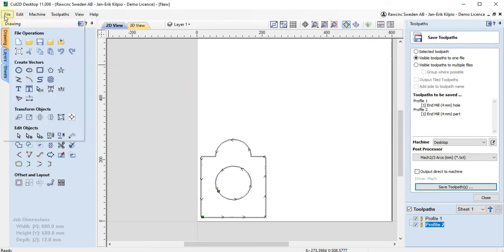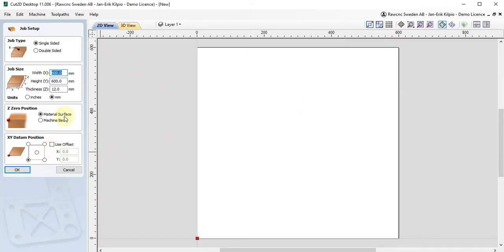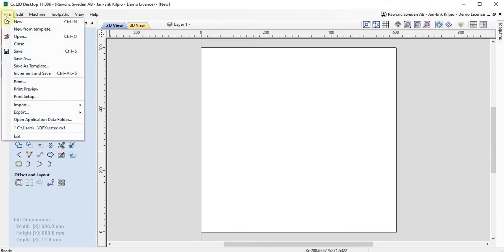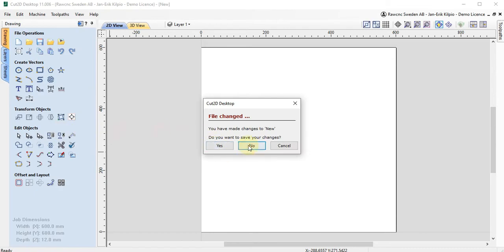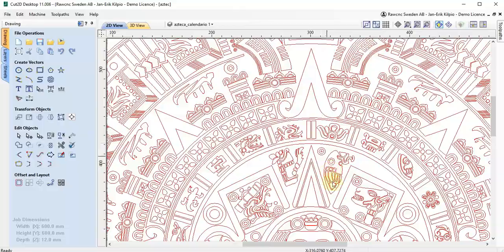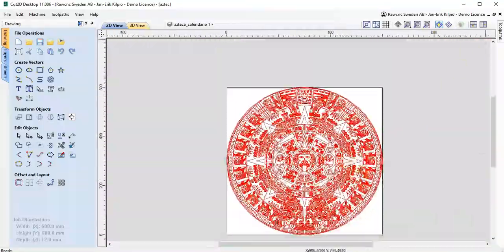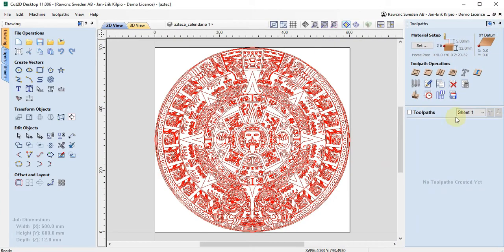Let's try one more thing. Create a new page in the same way as last time. This time we are going to import a file and create a quick engraving tool path. If you like this file, you can Google azteccalendar.dxf, and it should come up among the first results. Vcarve makes it easy to engrave complicated vectors, like these. Just select your vector and click Quick Engrave.